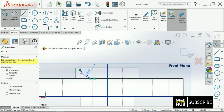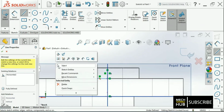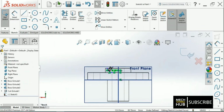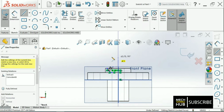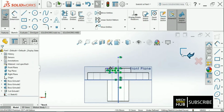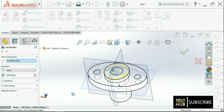Roughly, what you try to do is enclose this particular entity, followed by drawing a central line here, coming out of it, and exiting the sketch. Now you can take one more option which is already existing here, which is a revolved cut. Now have a look at your component.